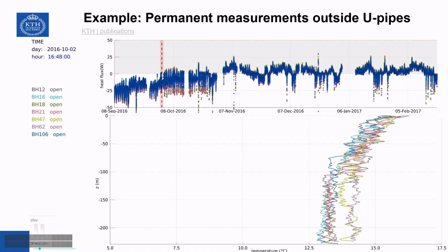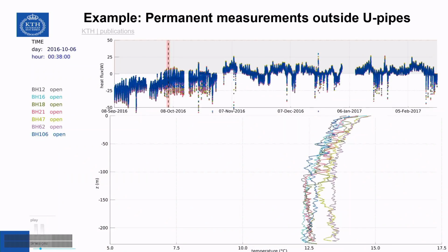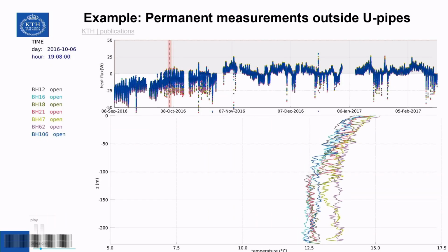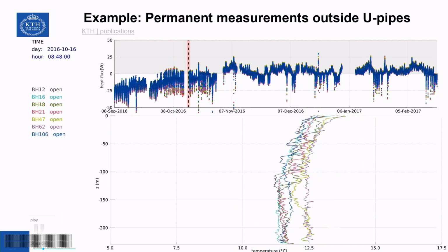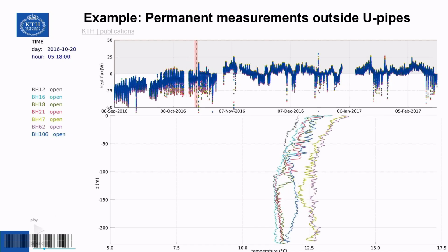In this case, we were starting in early September. It was the end of the cooling season. The boreholes were relatively warm, and now as we move from the cooling season to the winter season, you see that the borehole starts cooling down. And this is quite typical.